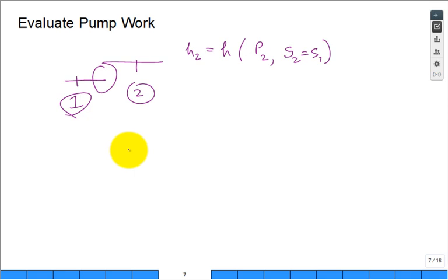And some people might say, hey, this is great. Because this is now compressed liquid, you would use the table for compressed liquid water, and I think that table is A5. But table A5 is not very refined. It's like, oh, you're at 10 megapascal or 20 megapascal or something like that. So a lot of times you would have to interpolate if you really wanted to get H out of table A5 given pressure and entropy. And we're going to go through that in detail in a second.